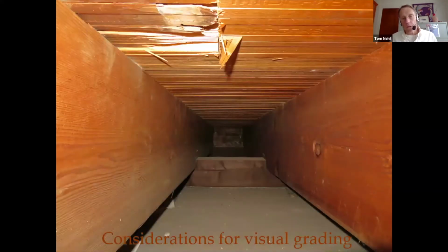So if somebody cuts a hole in a ceiling somewhere and says, stick your head up and take a look and tell me what we've got, you might see something like this. I can see one side of two joists for part of their length. And what I'm seeing here looks pretty good, but how much confidence can I have that this is representative of the rest of the building? Not much until we do quite a bit more sampling.